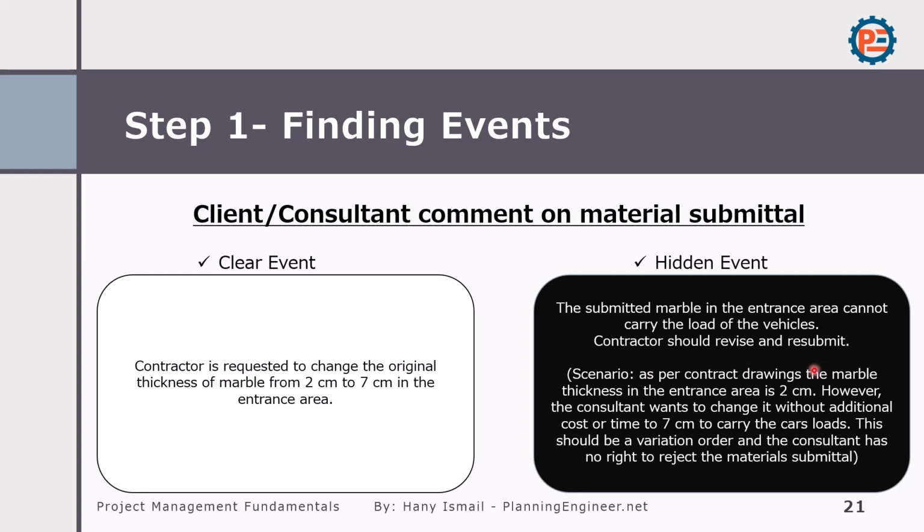Here, as per contract drawing, the marble thickness in the entrance area is 2 cm. However, the consultant wants to change it without additional cost or time to 7 cm. This definitely could be a variation order and also an associated claim.